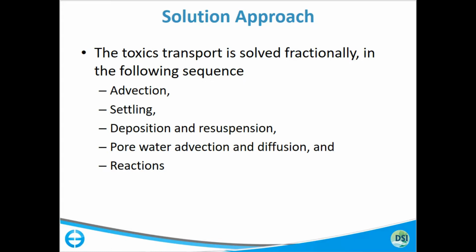And at the end of that process, you apply a settling process. Now material in the system at the end of the advection diffusion step is settled with the particulates that would have settled. Then you add a deposition resuspension step at the bottom layer between the sediment bed and the water column, and move mass either from the water column to the bed or vice versa. And then you have pore water advection and diffusion.